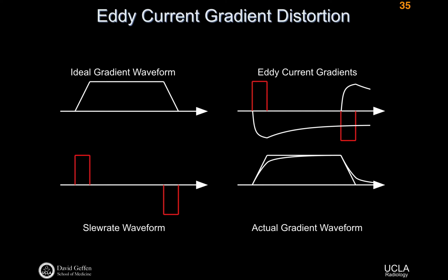And that's actually a really good point, right? So the Gx, let's say that this is Gz, Gy, and Gx. The x gradient could induce a field along the y direction, right? It depends on what structure it imparts a current and induces a current in. And the conducting structures that the current's induced in may look a little bit more like a y gradient than an x gradient. Who knows? It's the cryostat, right? So in principle, any gradient could actually produce a field along any direction. And so you're right, that could give you shifts.